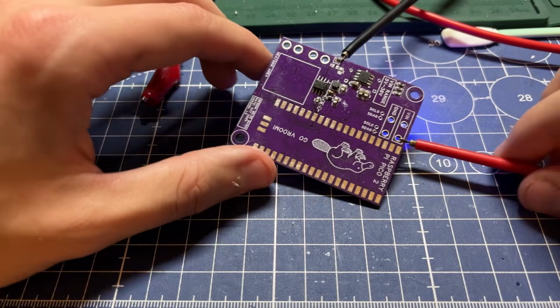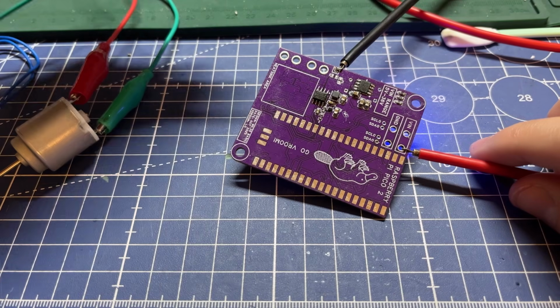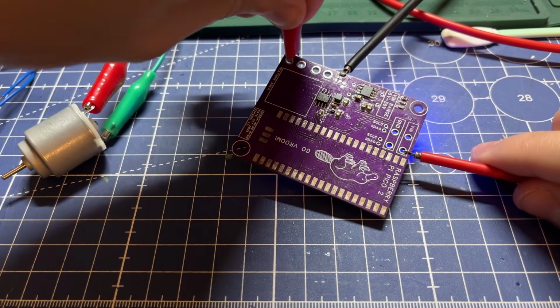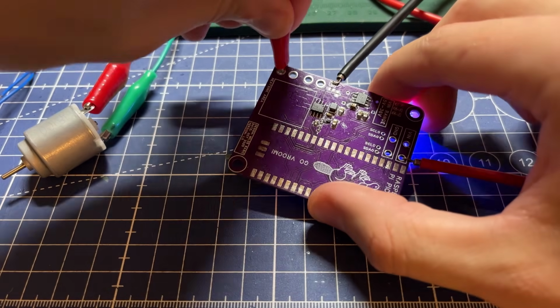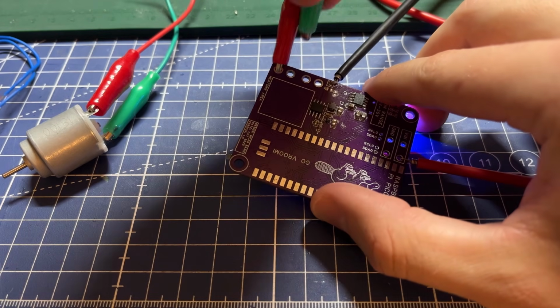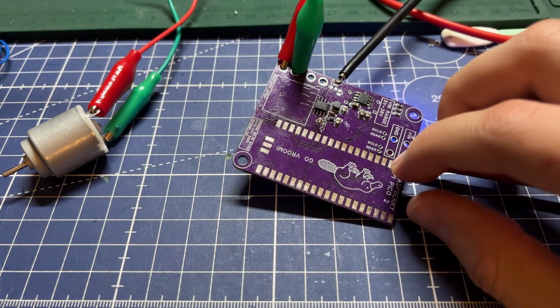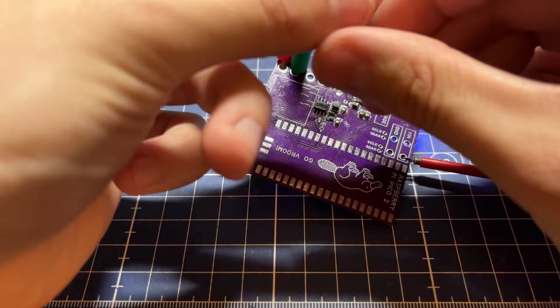Okay, so we have already tested the power supply, and you can see the board is on by the glowing lights. Let's connect the motor to one of the motor connectors. I'll just use some alligator clips, and I'll show you one of the H bridges. As you can see on your screen, I still haven't soldered on the microcontroller, but we can spoof it using a piece of wire.